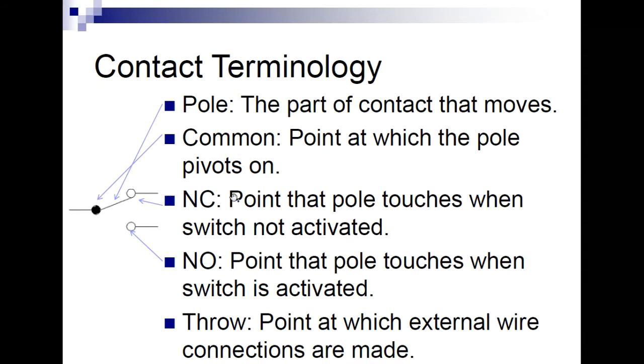So if you wire the normally closed connection, then when nothing is there, it's sending a high to the robot. If you wire to the normally open, then as the part comes and pushes the arm down, it moves the pole down and makes contact. So when the part is there, we send a 1 to the robot. So we can wire either one of these into the robot.